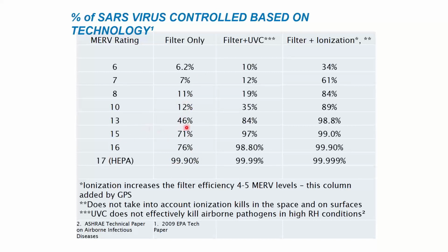This is kind of how ASHRAE came up with that Merv 15 or Merv 14 recommendation a summer and a half ago for COVID, because that got them a little bit better than 50% capture rate on the COVID viruses that made their way back to the filter. And they said if you can't get a Merv 14 to fit, then you can go ahead and do a Merv 13. It's not bad. Anything less than a Merv 13 is pretty worthless for catching this stuff this size.